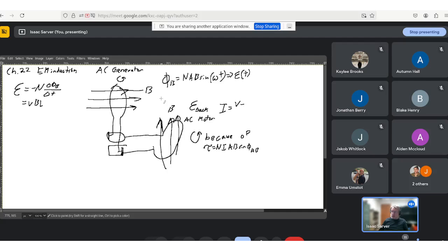So you've got a voltage that you're applying to this electric motor, and then you subtract off the back EMF from this guy here and divide by the resistance in the motor. So the current that you actually draw would be less than what you would have expected otherwise because of this particular effect.